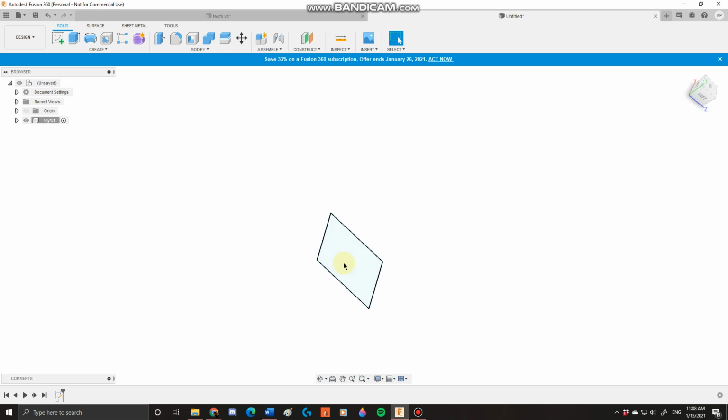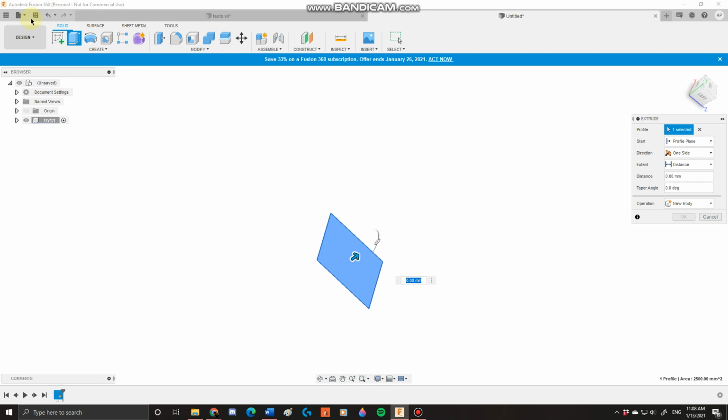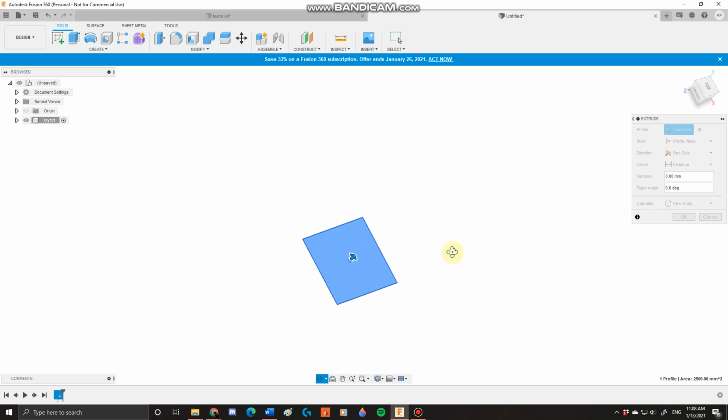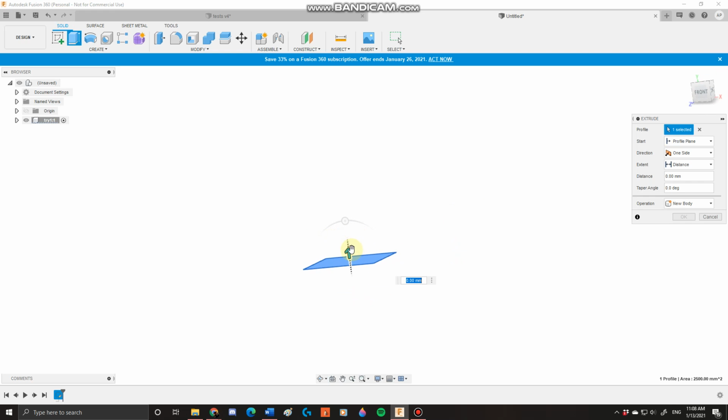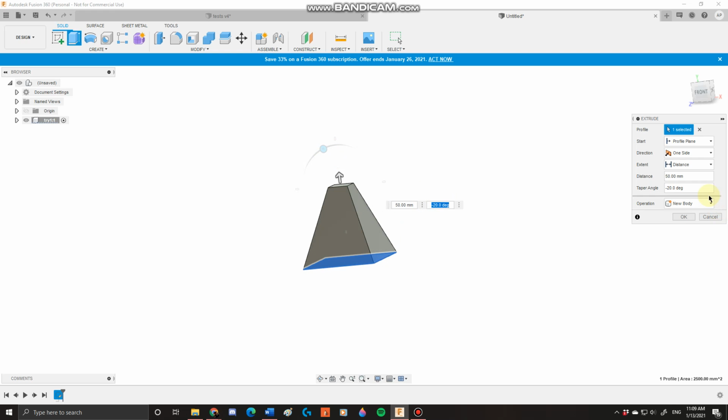To create our shape, we'll click on this face, go to our Create toolbar, go down to Extrude, and click. There's a lot of different options there that I'll teach you how to use in future tutorials, but for now we'll do the easiest thing, which is Extrude. To extrude, you'll see a set of components pop up, which is this arrow here that details how high you want your component to go, and an angle which creates either a cone, inverse, or outwards.